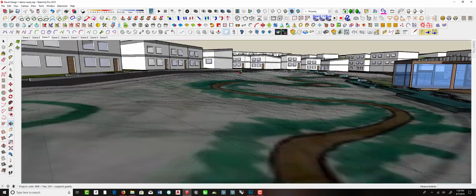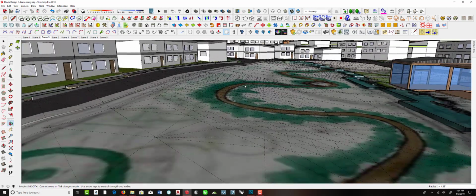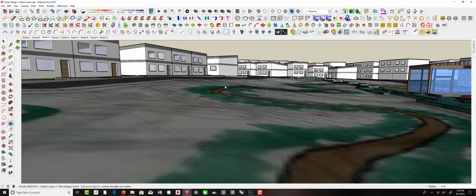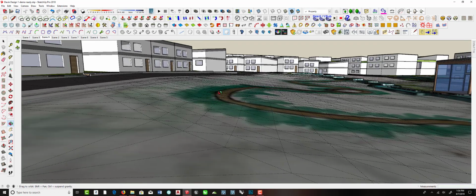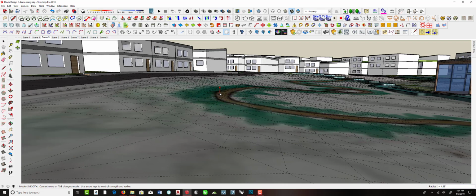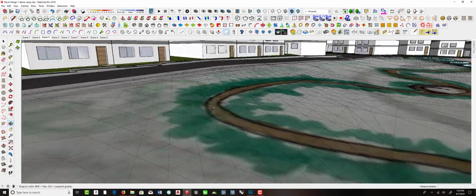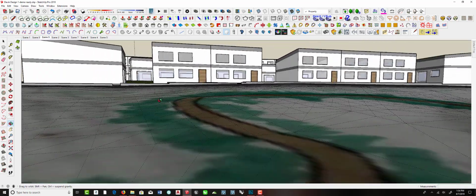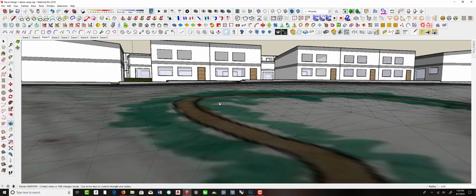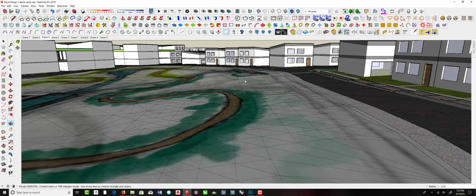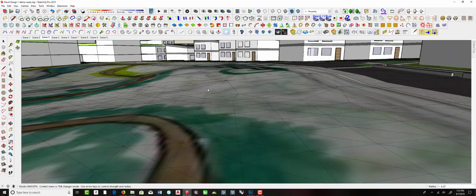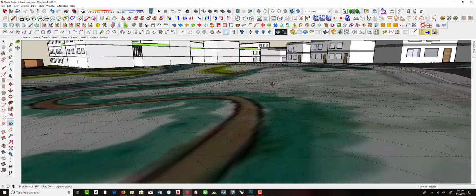Okay, so it's really important that you go through and do this process before you split the terrain. You've got the image on here, and if you had drawn something up in AutoCAD and you had the vectors, then just export it or plot it as a PDF, or do a snipping tool screen capture, just get an image of it and map it onto the surface. That way you can do all this grading beforehand, and then once we split this, we'll have it ready for the materials. And you just have to keep looking around and adjusting things to make sure that everything's fitting. So that looks pretty good.